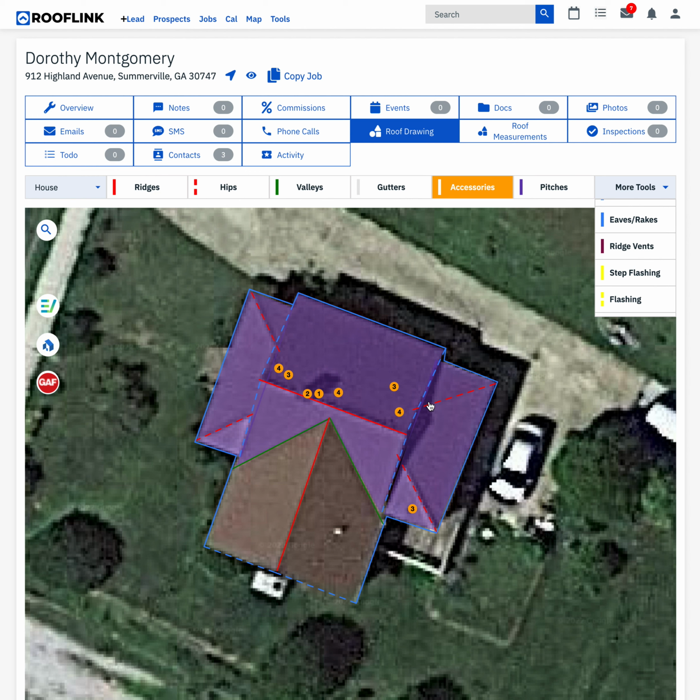So right now we know that this roof is pitched this way, this is pitched this way, so this is the way the water's running, and the water runs off this way. So anytime a sloped area of a roof meets siding, which it would meet siding in this area all the way across, because this is dropped below the actual roof line and it's running into the siding of the house. Any place that an area is sloped, it's going to need step flashing.